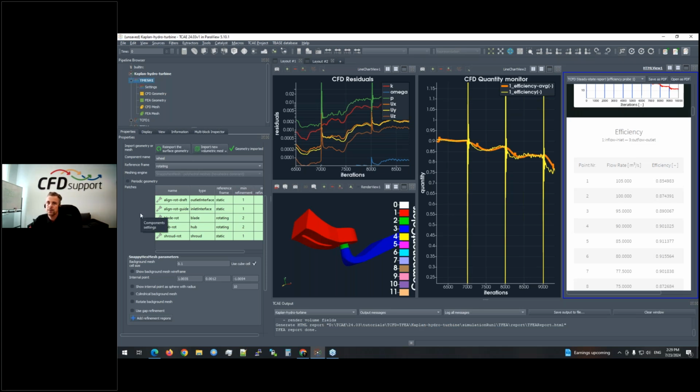The issue with fine meshes is that the convergence process takes a lot of time, and then you're losing your time. So I recommend quick iterations in the beginning on the rough mesh, and then refine when you are sure that the model is performing the way you would expect.